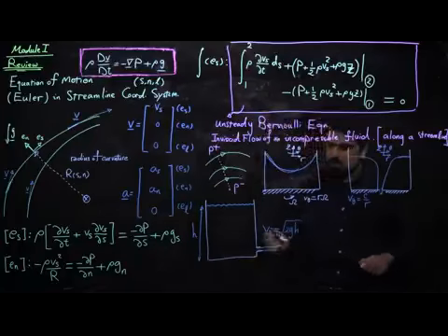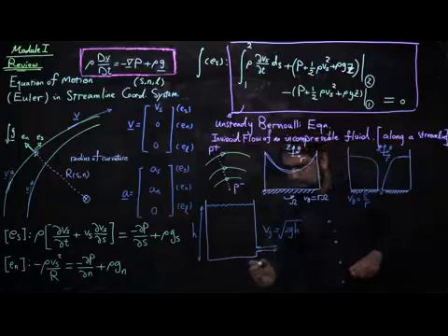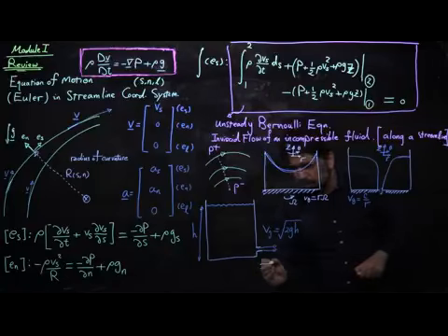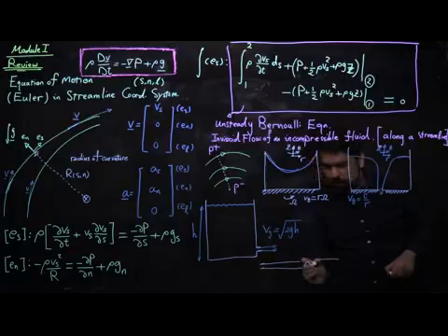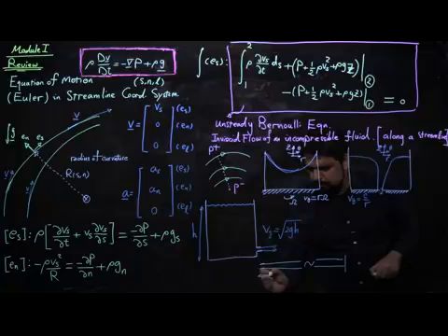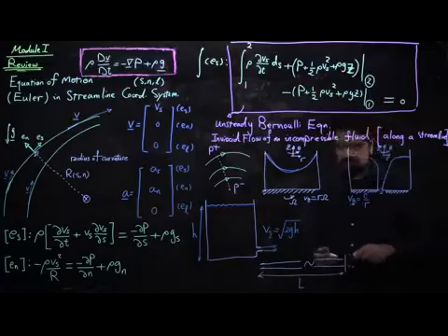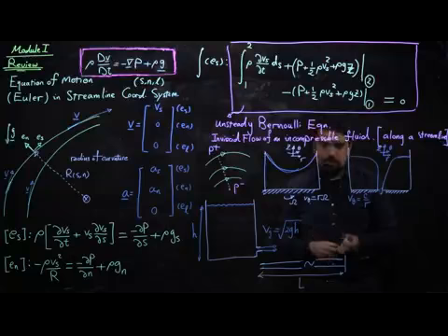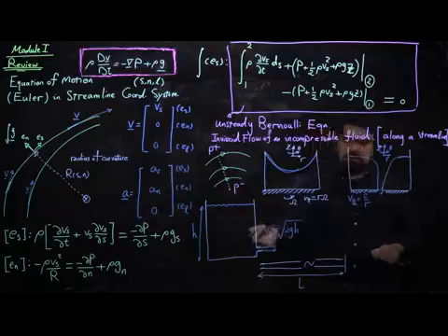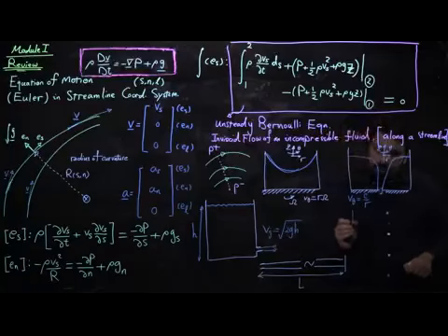But if we like to look at, for example, a transient process where the orifice is not short but rather long, so this is a long pipe that has a length L, that at one end is closed, and all of a sudden at time 0 we open it, we saw that velocity is not anymore the square root of 2gh.